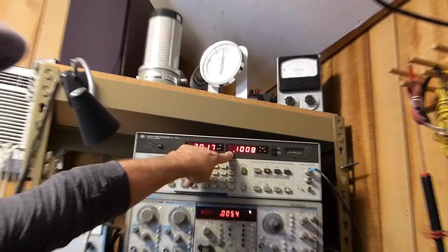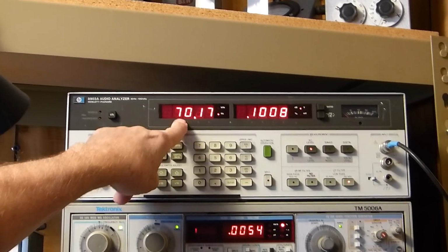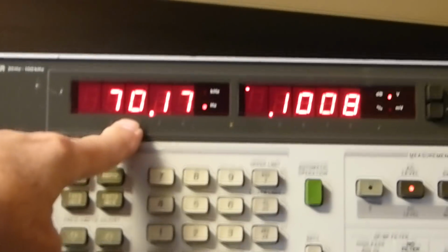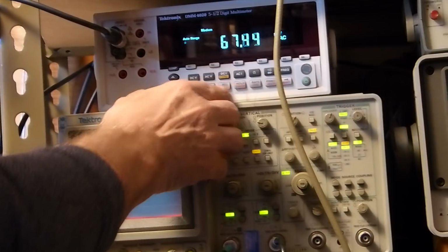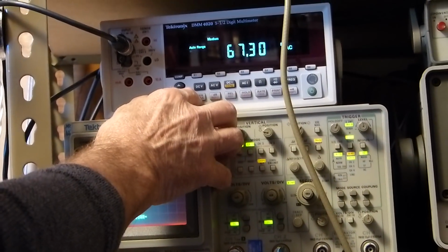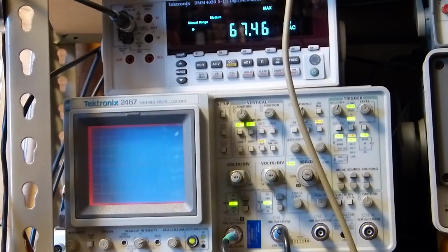Our voltage up here didn't change. Our frequency didn't change. The 70.17 is not important. I'm just trying to set it on 70. But I've got a variable, you know, I can vary it, so that's as close as I can get. But I'm putting the numbers in exactly as I read them. Our resistor's still 10,000 ohms. There's our voltage. Now we've got to measure this voltage again. Go back to rate. Let this thing run for just a second, right up here. And then we'll stop it at its max. That's 67.46 millivolts. Let's type that in.